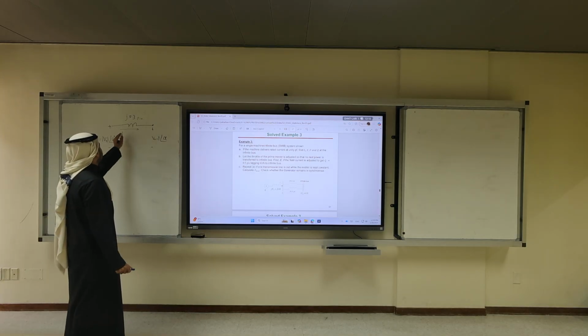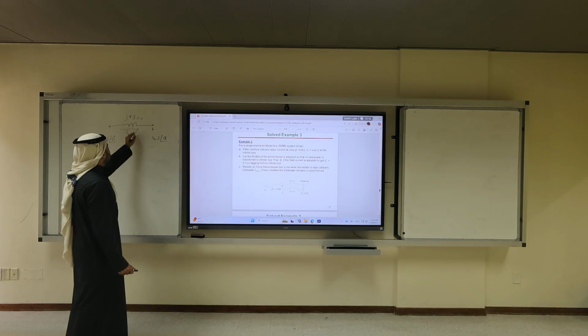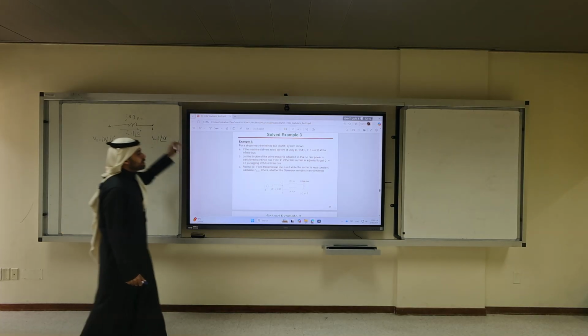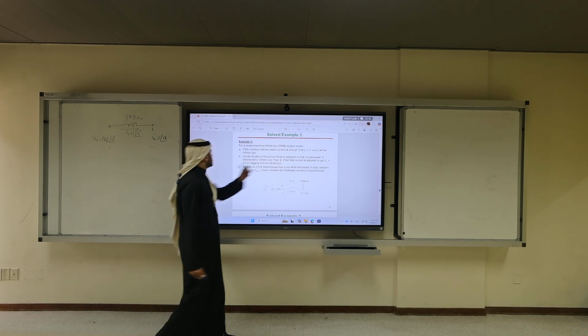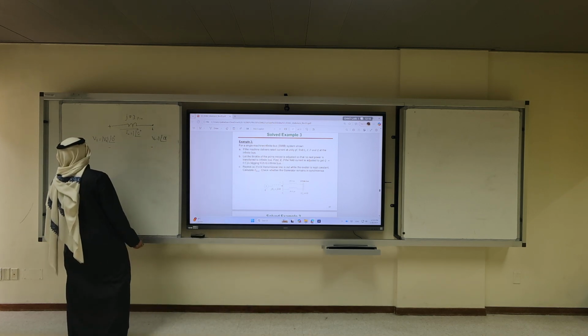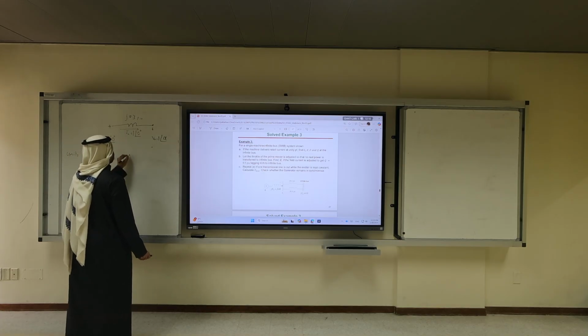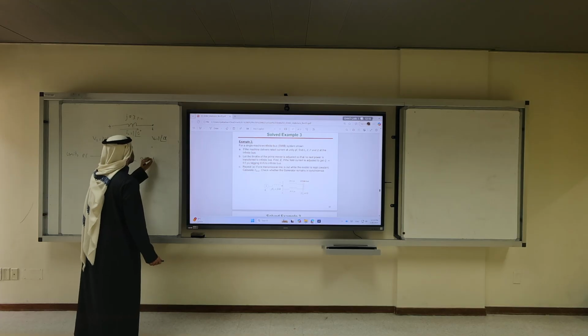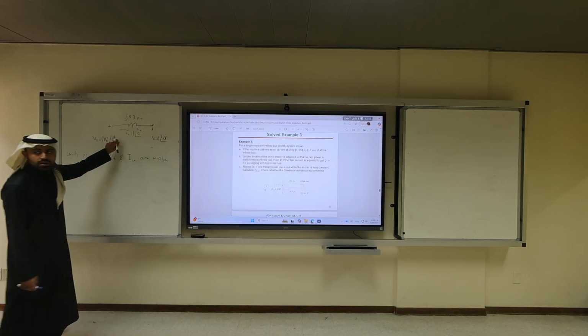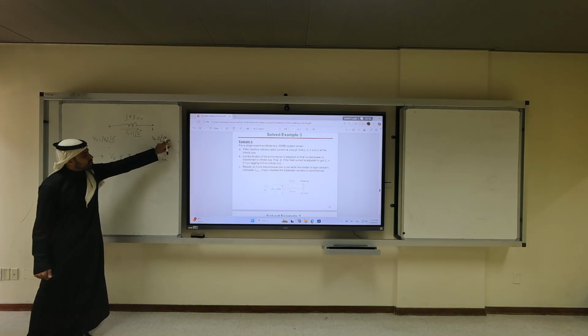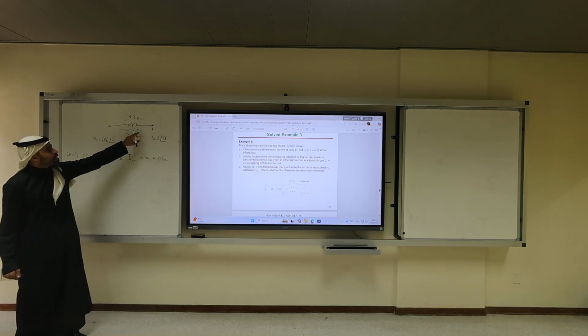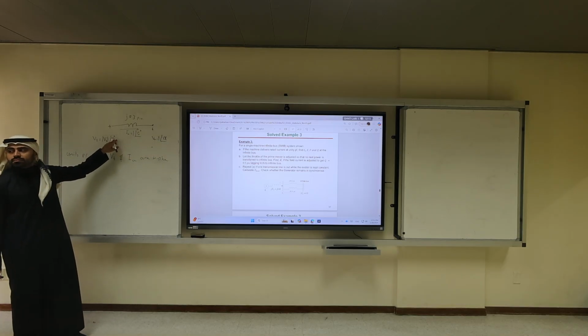So here what do we have? IA is what? Is 1 at an angle of 0. Why at an angle of 0? The key here is unity power factor. Unity PF implies V of t and I of A are what? In phase. So that's why this is 0, this is 0. If you take this as a reference, let's say VB as a reference, this will be alpha and alpha. Get it?